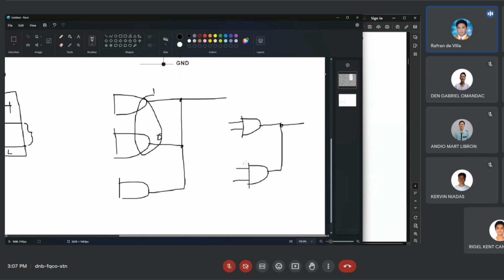For what purpose would you connect their pins together? Let's say, for example, you want to create a 4-input AND gate. You can create a 4-input AND gate by performing this connection. Why this connection? It won't short. If one is high and another is zero, what happens here is that the high is equivalent to an open circuit.